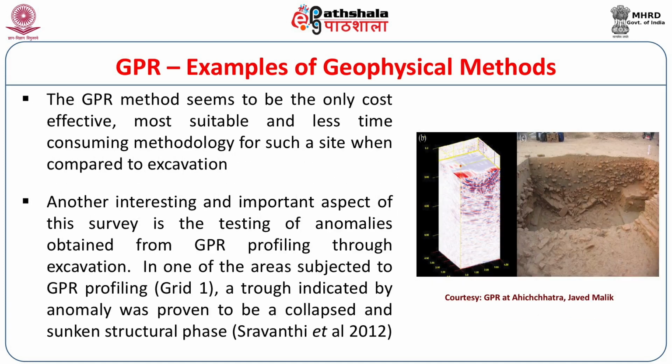So you can see in the adjoining slide, one is the ground penetrating radar results. You can see the slump. There is a slump there. There's a red color. There's a slump there. So when this result came, to confirm the results of the ground penetrating radar, immediately an excavation was carried out.